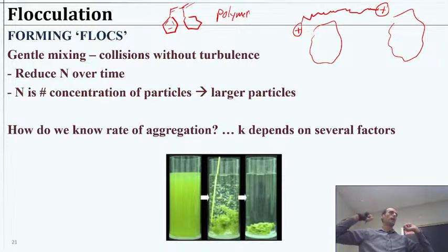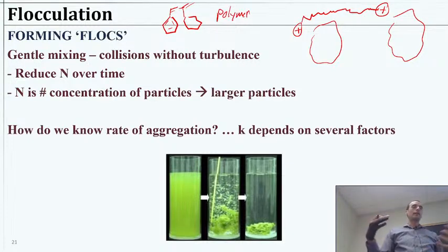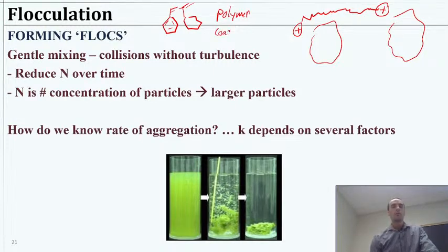And so if we add in some polymers that have charges like this or are generally sticky with respect to the particles, then they can also help destabilize a solution. So polymer coagulants are fairly often used. Similar principle, so I just wanted to make that little note here. There are a few other ways we can manipulate the particles' stickiness in that manner. So you'll see that in practice.